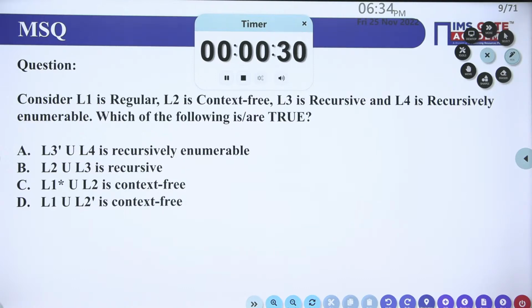You will have additional shear force. Now, my dear students, a question can be asked: sir, how can you avoid torsion? My dear students, some part of the torsion will be taken care of by the shear. If the torsion is high, then we provide closely spaced bars. We will reduce the spacing. That is the best way to avoid torsion.